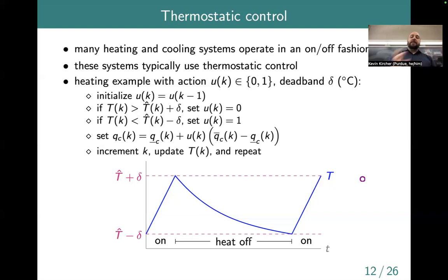Let me talk about some situations where you would see something other than thermostatic control. One would be if you don't have equipment that's either off or on, but equipment that has multiple stages. For example, in one of our test houses, we have a heat pump that provides most of the heating, but it doesn't have enough capacity to keep the house warm on the very coldest days. When it runs out of capacity, it turns on a second stage of heat, which is electric resistance heat, just a big hunk of metal that you can run current through to get heat out of it. So there you would need additional logic.